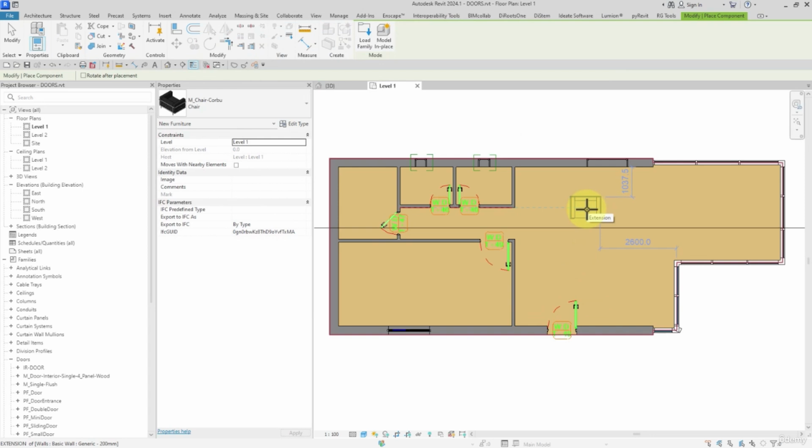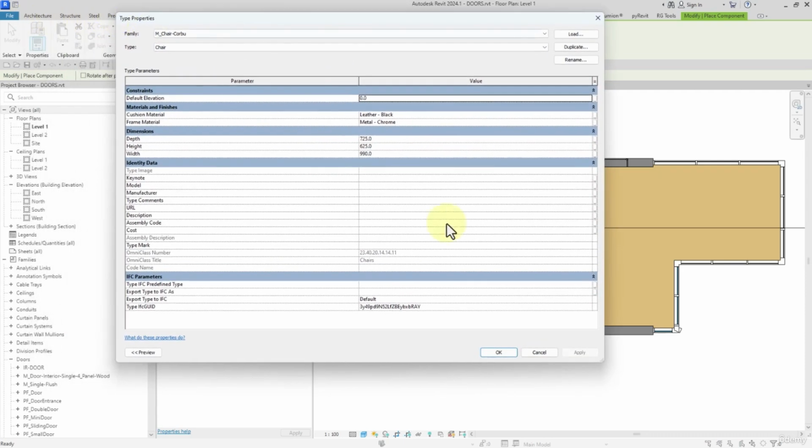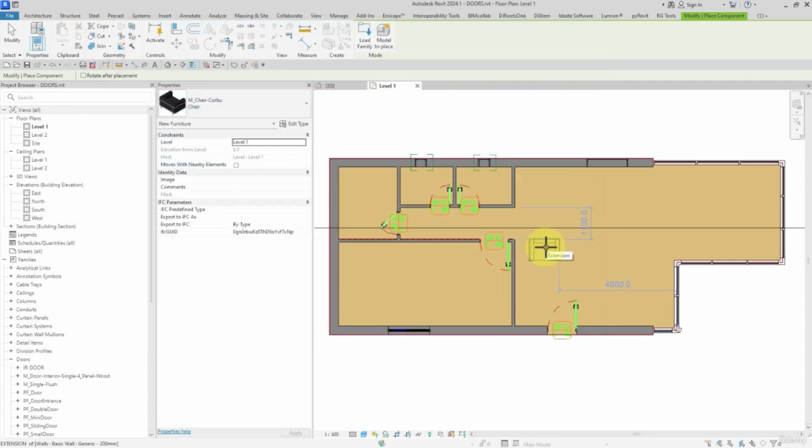And note that the loaded components in the project might behave differently, since we got a wide range of elements which are considered as components in Revit. As you are aware, some of the families got some simple parameters while others have more complex parameters, and some elements are only created without any provided dimensions and so on. These are common. Okay, so these things are just the standards in Revit, not the exceptions actually.